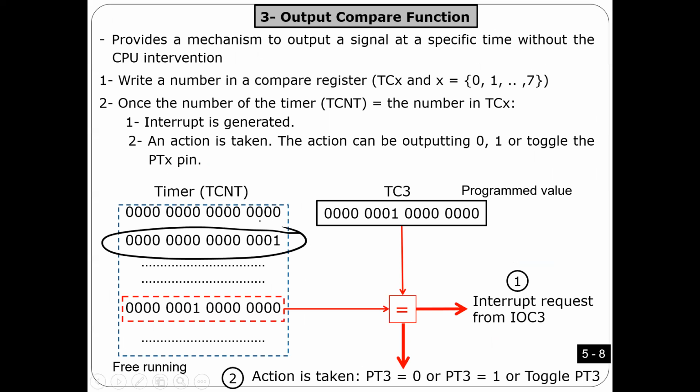For example, right now we're at count 1. Then I'm going to store a value in the future, for example 900. So currently I'm at 1, right? Then I'm going to put the future value in TC. This time I'm going to write to TC, not read. I'm going to write 900 in TC. Is that okay?